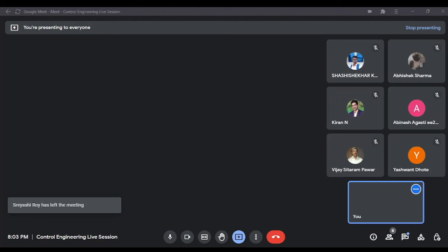So now we can see the information about it. Step info TC3 and step info TC4. So for TC3 you can see that settling time is 0.32 and which is well within our requirements, but the overshoot is 9%. So we still want better. Now for TC4 you can see settling time is just under 0.2 seconds and the overshoot is 4.7%, which is less than 5%.